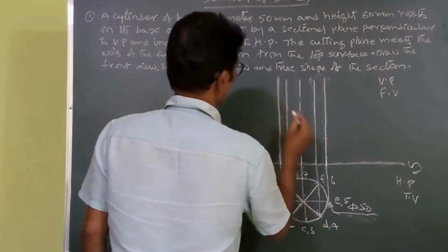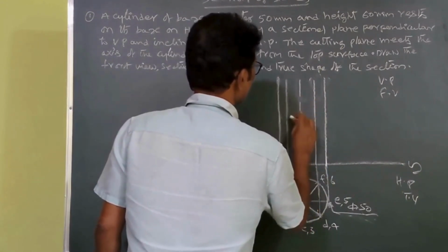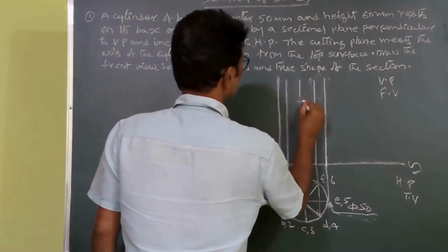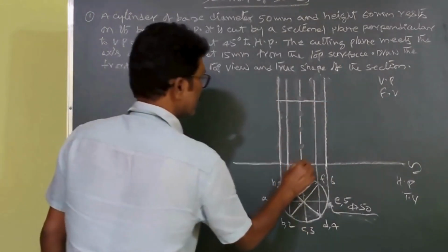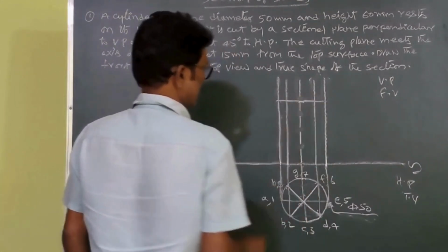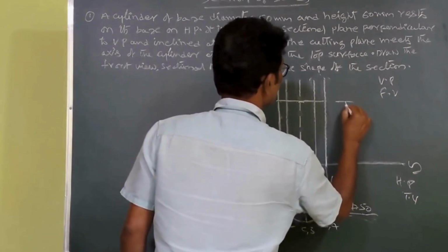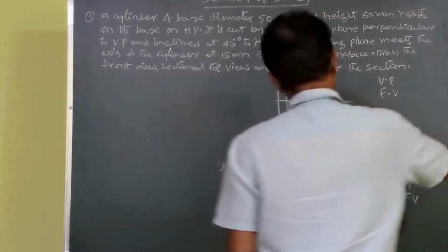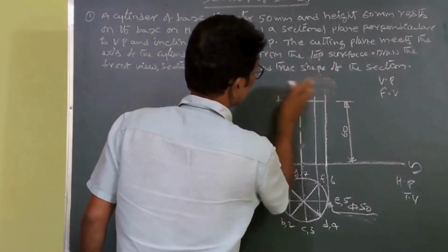So therefore, from here to here is 60. Here to here 60, as a distance. You cut it at this point and draw a horizontal line parallel to xy. From here to here 60, you cut it at this axis and draw the horizontal line parallel to xy. So this height is equal to 60. Okay. Now I want to remove this top.